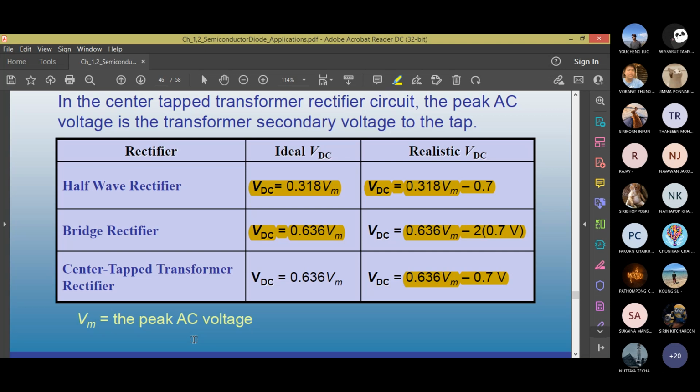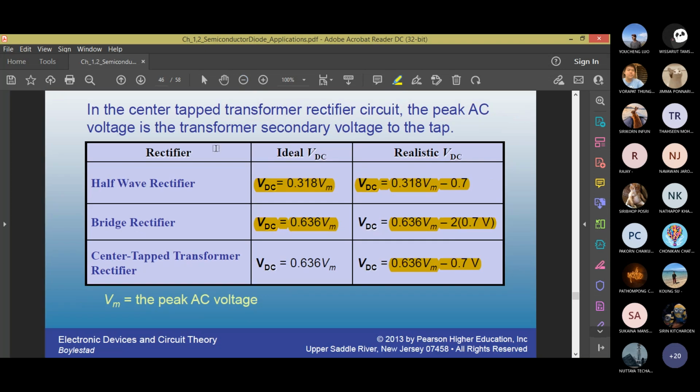That's the diodes application in rectifier, which is a part of power supply. What is a power supply circuit? The adapter that I'm using now is a power supply. It takes AC from the wall, steps down the AC using a step-down transformer, and then the rectifier makes a peak like you have seen just now. Then inside this, there should be a capacitor filter, and then an additional filter stage to make the output not look like a wave but almost flat. And finally, there will be an IC voltage regulator.